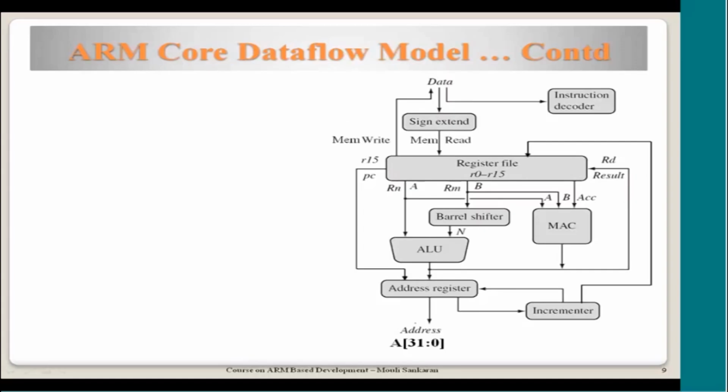Finally, what is written into a register has to be 32-bit data, because I told you the instructions operate on only 32-bit values in the register. So even if the memory interface allows reading 8-bit or 16-bit data, that either gets sign extended or the top portion of the content is filled with 0, and the complete 32-bit content of the register is used for any arithmetic operations inside the processor.